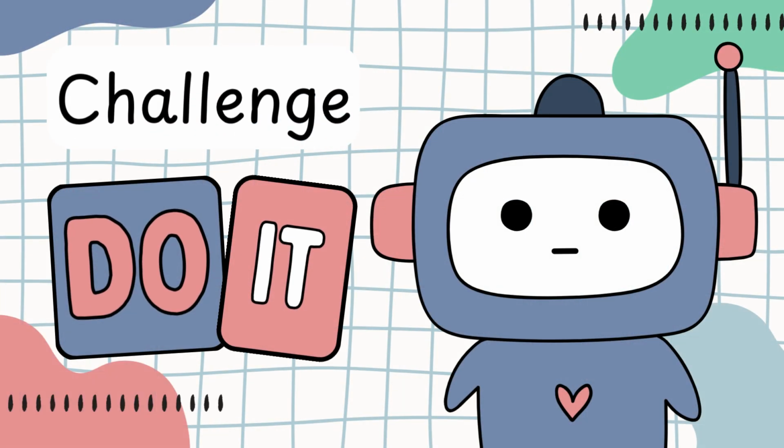Now that you have successfully coded the display for numbers 0, 1, and 2, it's your turn to continue the sequence. Follow the same method we used for 0, 1, and 2, to write functions for the numbers 3 through 9. Make sure to turn on the correct segments for each number using digitalWrite HIGH, and turn off the others with digitalWrite LOW. Test each number on your 7-segment display as you go, so you can see your code working in real time. While testing, use the snipping tool or any screen recording tool to capture your display output and upload the video.